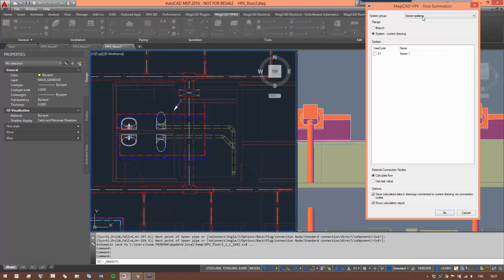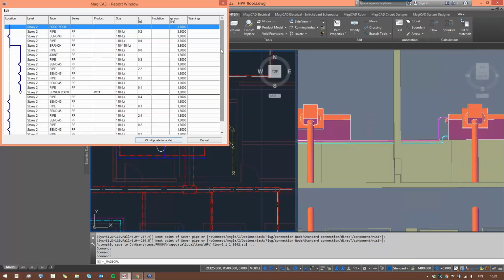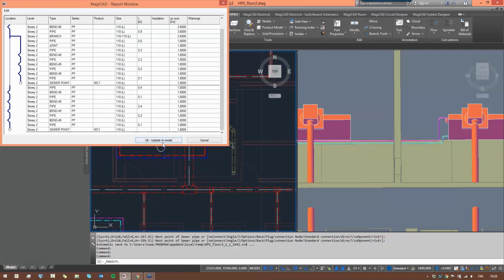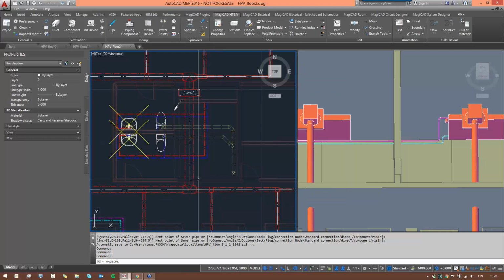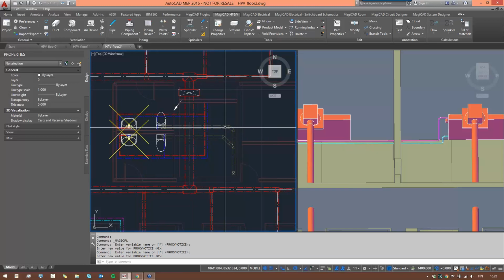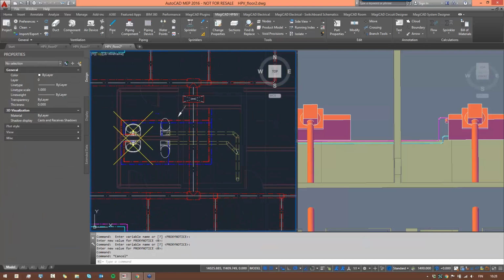The calculation options that we have for sewer is only flow calculation, so of course didn't select that one. There we go. We can see what the flow is, and the sizes are then just 110 locked. Part outside of flow routes. Okay, yeah, it's those water basins there. Don't have to worry about them. The information is still saved to these. We can still use those.